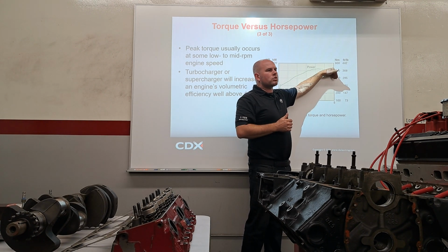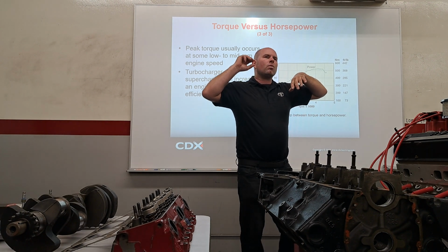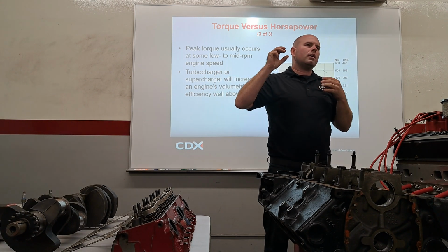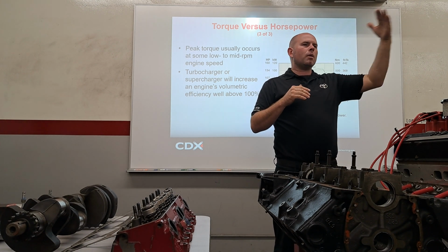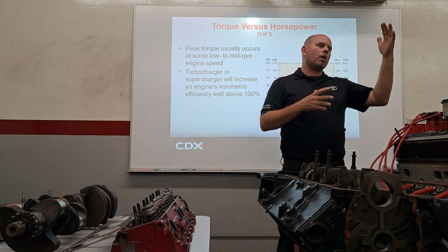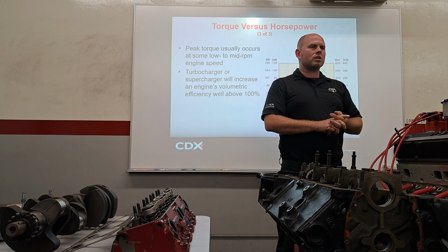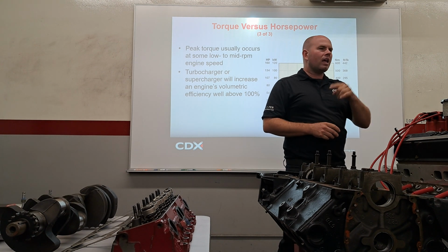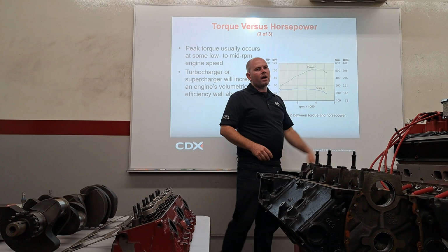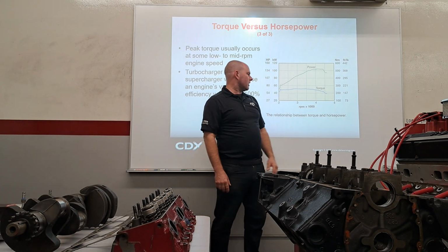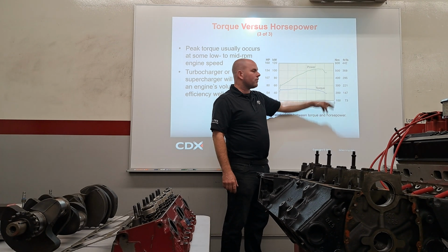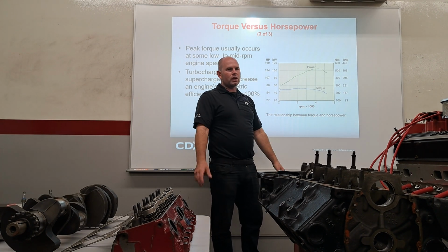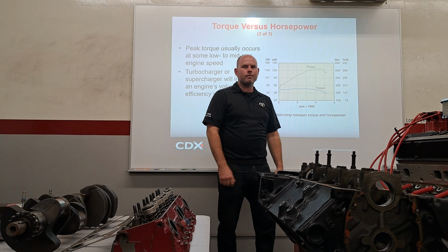You lose a lot of volumetric efficiency, even though, remember, when we talk about power, it's got to do with RPM, right? So the higher the RPMs, more helpful, right? But the higher the RPMs, the less volumetrically efficient it is, so we start actually losing power. At some point, all the engines are going to drop off. They're going to lose power. So at that point, we're like, you know what? In this case, we really don't need to go over 4,500 RPM. We're done. We're just going to rev limit it right there.